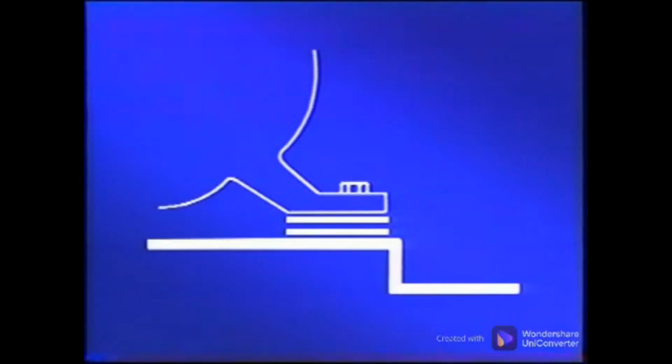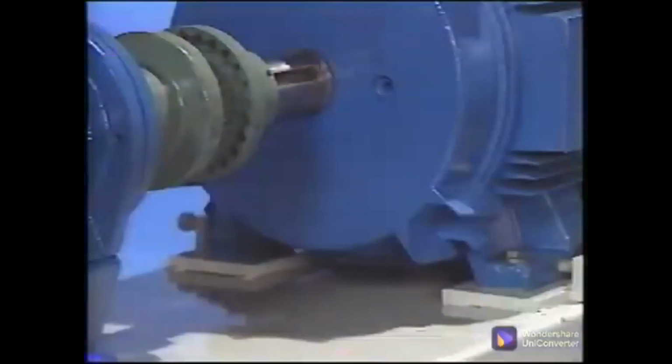There should be no more than 5 shims under any foot at the same time, because the stiffness of the foot decreases as the number of shims increases. If several shims are to be used on a foot, sandwich the thinner shims between the thicker ones.